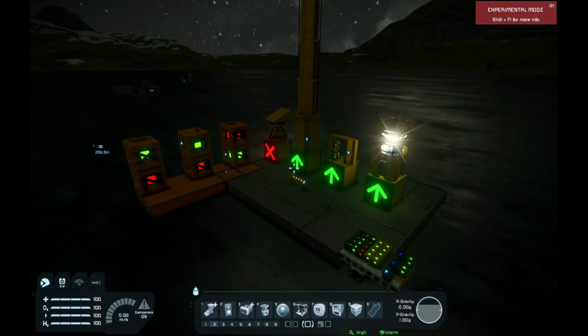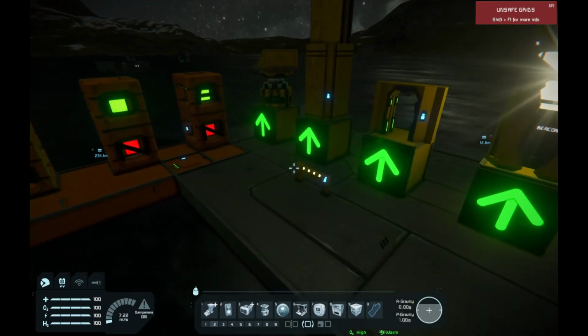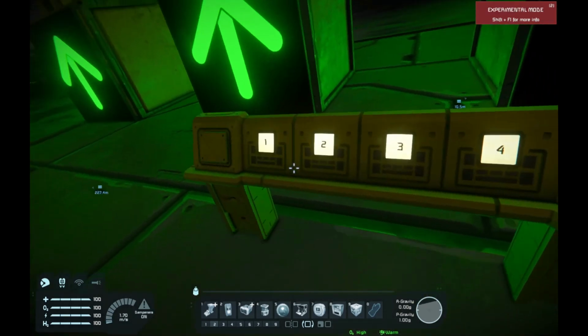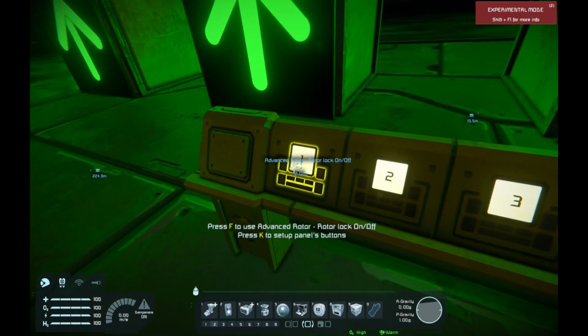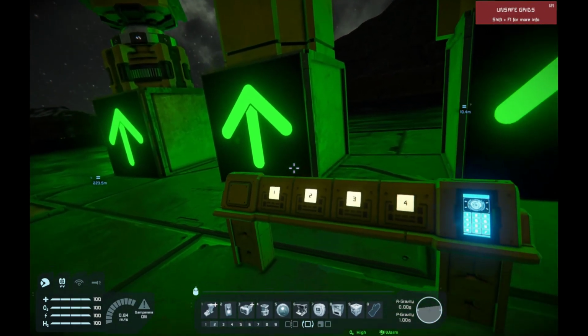Large orange timer blocks on the left are the outputs, from right to left: AND gate plus NAND below it, OR gate plus NOR below it, XOR gate plus XNOR below it. AND triggers when all the inputs are true, OR triggers when at least one input is true. XOR triggers when at least one input is different than the others.